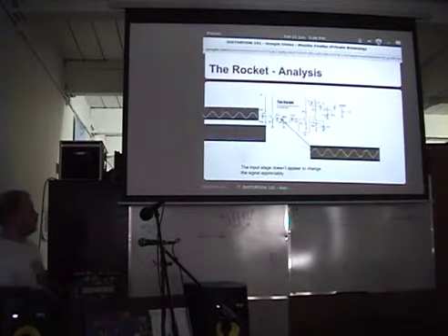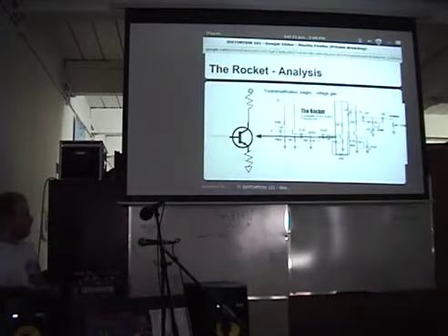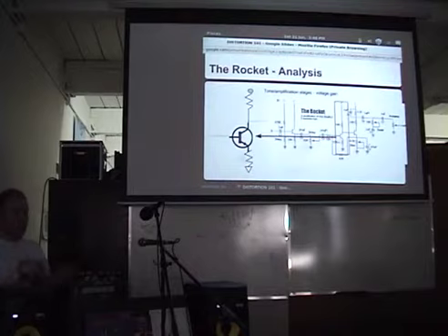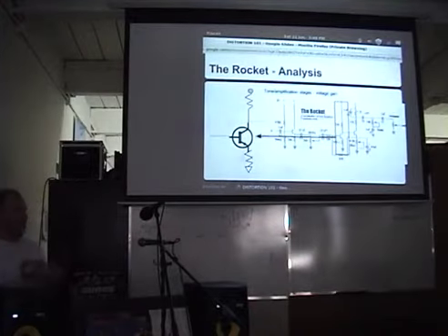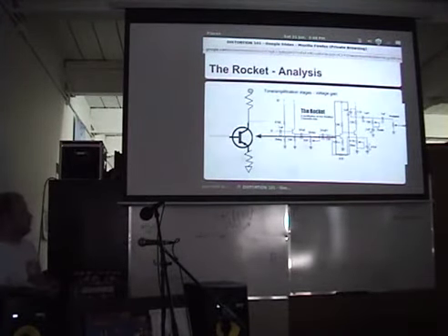Anyway, so that's the input stage. The tone and amplification stages are where it gets interesting. So you'll notice there's a common topology between these two transistor circuits. Each one's acting as an amplifier. It's a general rule of thumb: each transistor, at least in these circuits, is doing an amplification of something, be it current or voltage. So these guys are in charge of making the signal bigger, in the voltage respect.